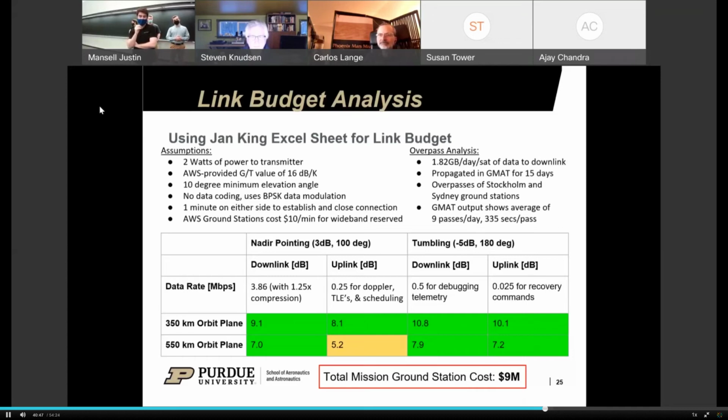So we opted for a lower gain but much higher field of view patch antenna. And so the compression rate was really just trying to get those data numbers down because we had fixed power usage based on the capability of those antennas, and then a fixed gain pattern. So we were really trying to make the most out of those gain patterns by looking at what is a feasible data amount we can transmit, if that makes sense.